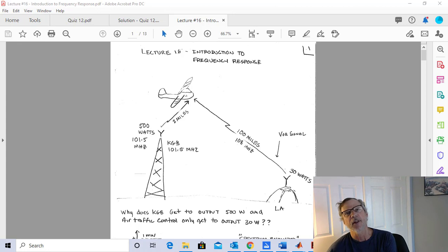I'm going to introduce one of the most valuable tools that I know for frequency response. It's called Asymptotic Analysis. And what it allows you to do is quickly get the magnitude of the frequency response at DC and then at infinite Hertz. So you can get the DC response and then the response at infinity. And you can do it really easily for the circuit, no matter how complicated the circuit is, well, to some degree. But then you can also do it for the transfer function.